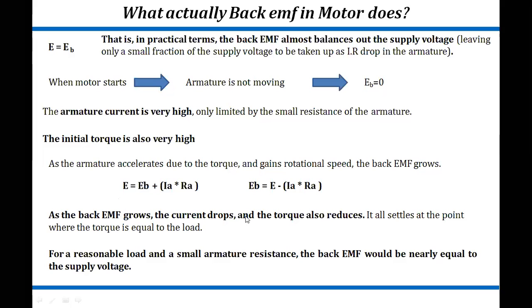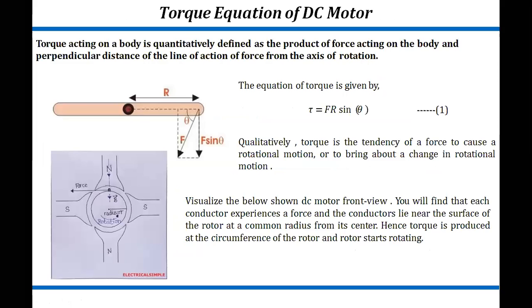So here for a reasonable load and a small armature resistance, the back EMF is nearly equal to the supply voltage. So we are supposed to study the torque equation in today's session. What are we saying about the torque?